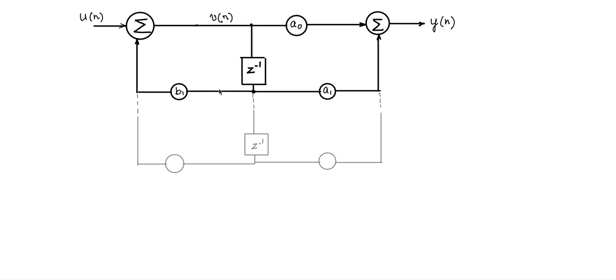Let that snapshot instant be kT, and first define the variable at the output of the unit delay, meaning first define the memory variables, because they are the state values, they remember. So always define the memory variables first. I will call this variable here v of k.